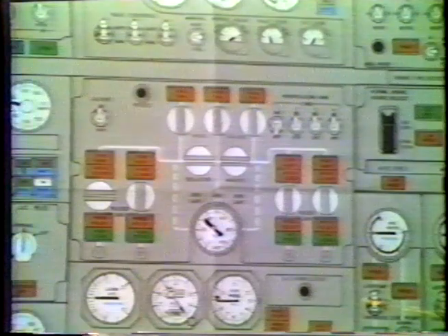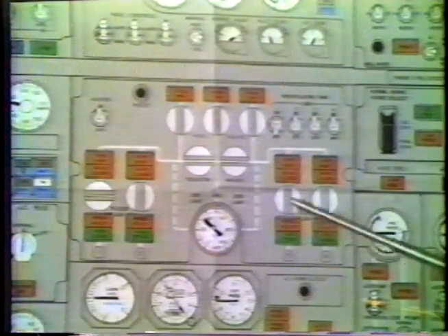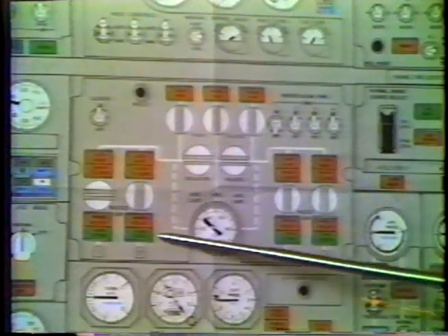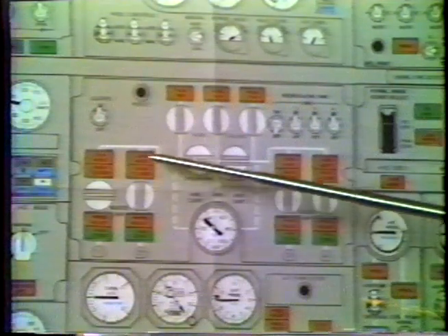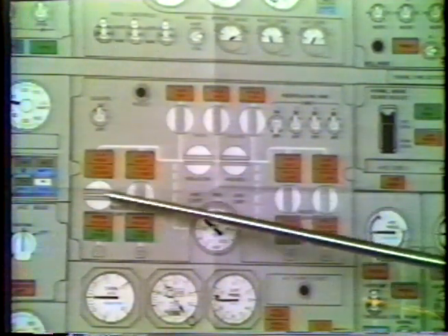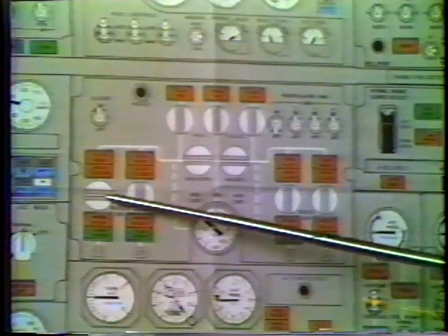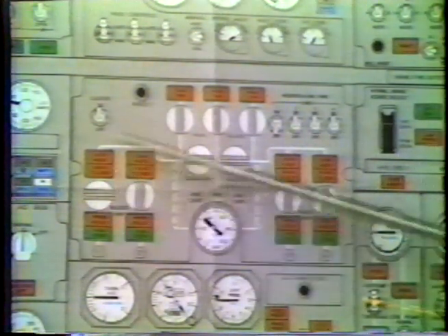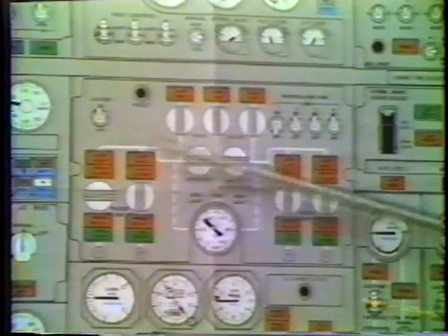At the higher altitudes, it'll be slightly higher than that. Above that point, the high stage light will go out and pneumatic air is supplied by the engine only with low stage. And of course, anytime you turn the bleed switch to close, you will force both high and low stage to be closed off to supply the pneumatic.